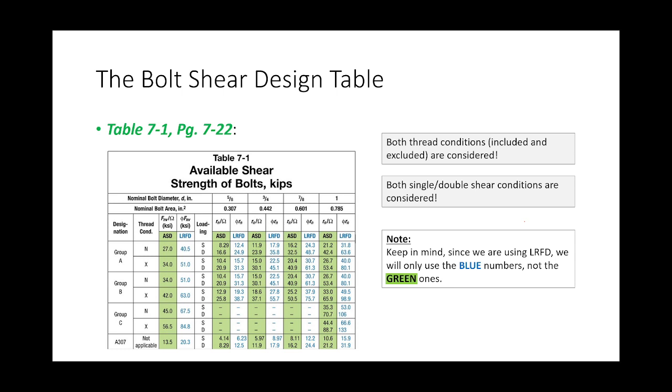This is a really nifty guide. We're actually going to use this region of the manual a lot because if you turn first off the page on the right is the tensile capacity of the bolts, and if you turn the page, you're going to find the slip capacity of the bolts. We'll talk about that later. Any questions?